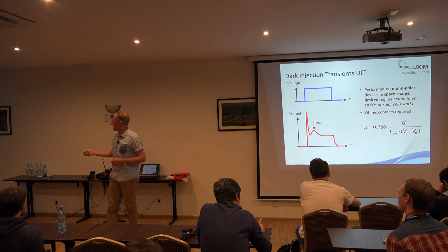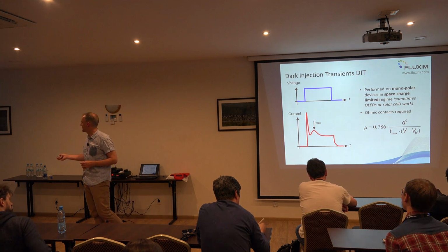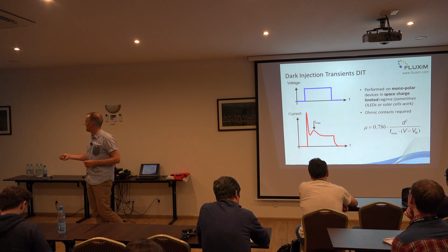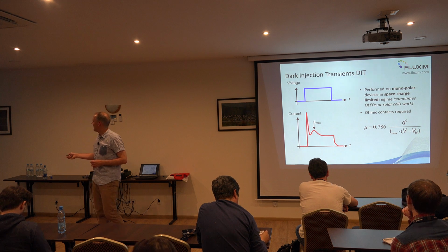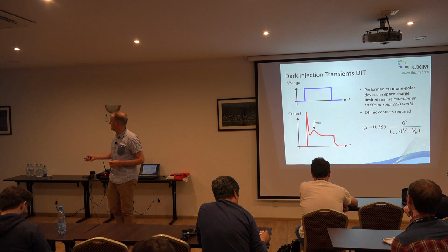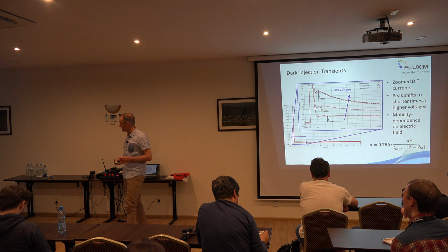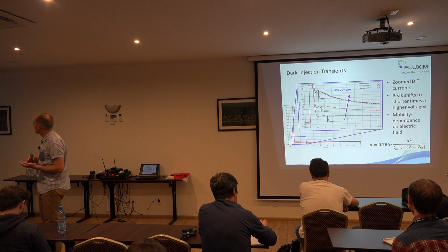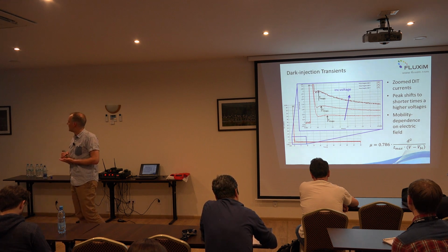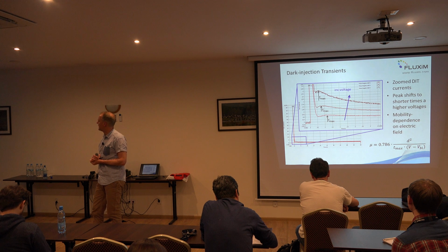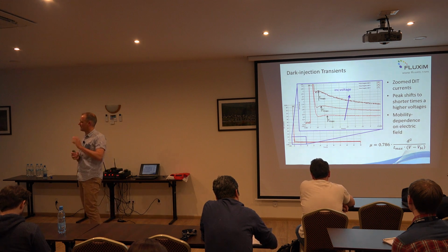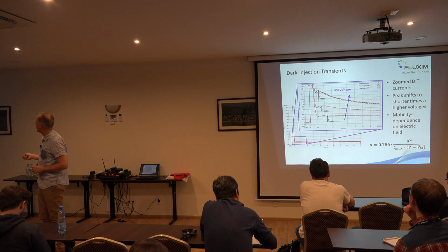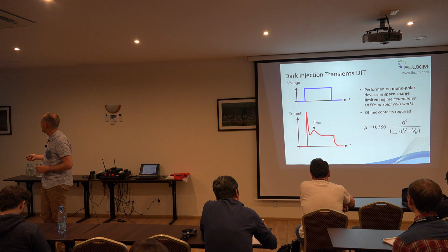But the formula to apply is: take the time position of the peak, multiply by the net applied voltage, and then use this simple formula to estimate the mobility. This can be done here with this data. I think that's an example of alpha NPD. It was about a 1,000 nanometer thick alpha NPD sample, and we have seen a nice signature here of the expected curve shape.